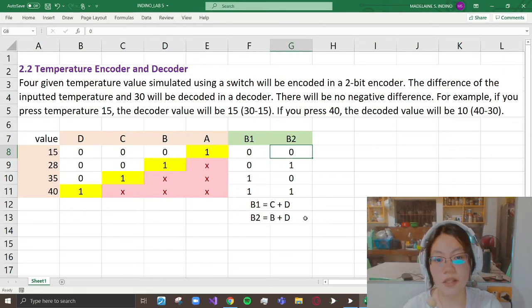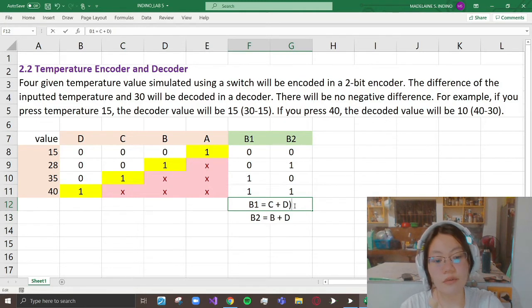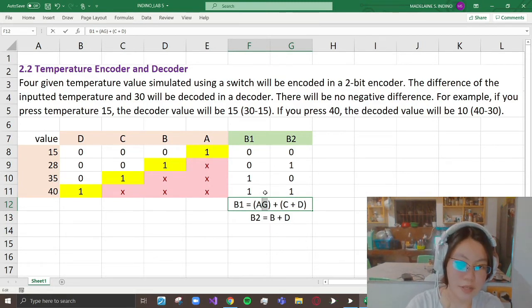So we will just use the identity law: anything that is ORed by itself is also itself. Therefore, we just need to OR either one of these 2 Boolean expressions with a 0 value that includes A. So how do we set A as a 0 value all the time? By ANDing it with a ground. The ground is the additional component in our circuit.